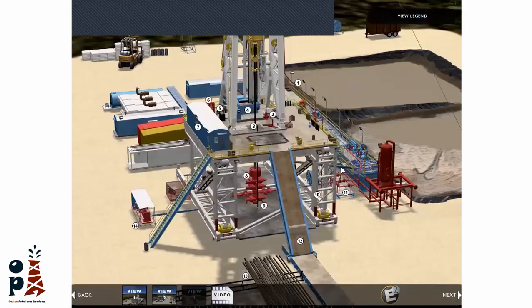This is the flow line, guys. Okay, I will respond to this question. What is the importance of the mud gas separator? I just said that the mud gas separator is used to separate the gas when we have a high gas content in the mud. You know, there is a difference between the mud gas separator and the mud degasser.